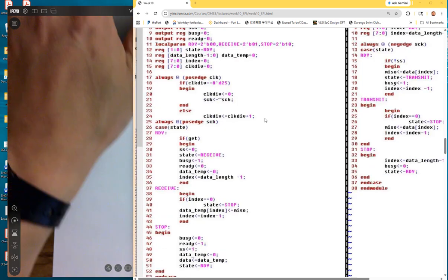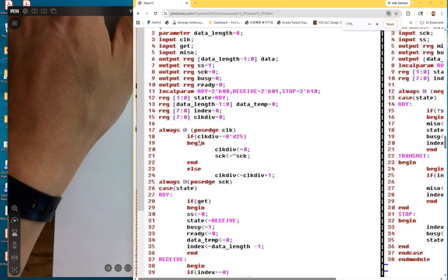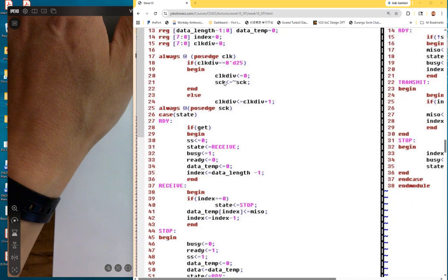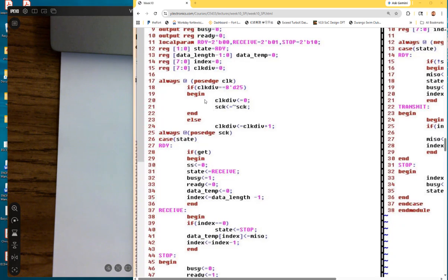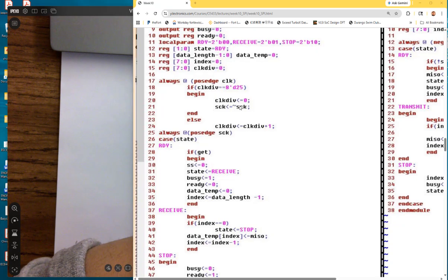And we already went through this on Tuesday, but let's just review this really quick. You can see that we have a positive edge of the clock, which is not doing anything but just defining the clock, right? So your FPGA actually defines the clock. You are not seeing anything on the ADC board or the PMOD sensor light sensor module. It doesn't have a clock, so the clock comes from your FPGA's code.